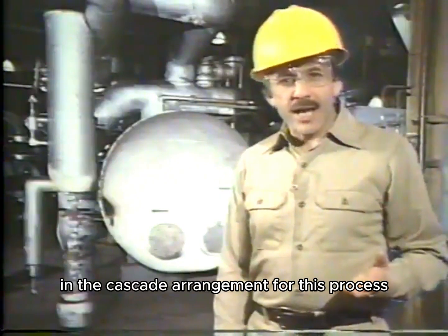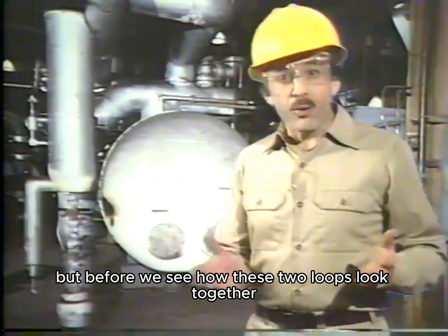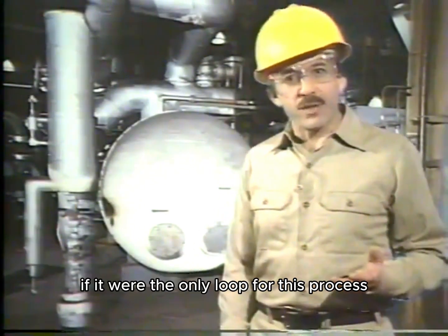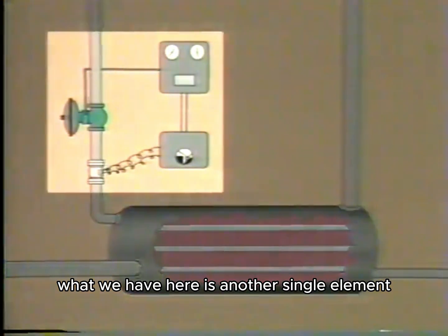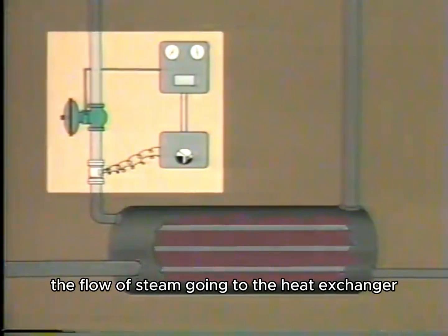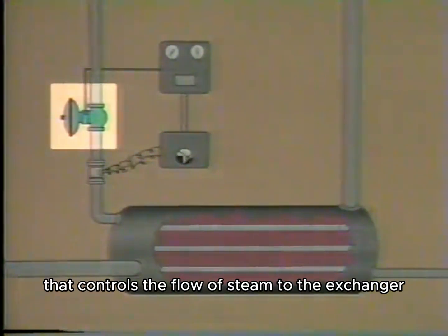Now, we said that in the cascade arrangement for this process, the secondary control loop is combined with the primary control loop. But before we see how these two loops look together, let's see how the secondary control loop might look if it were the only loop for this process. What we have here is another single-element control loop. We're monitoring one variable, the flow of steam going to the heat exchanger. This information is used to adjust the steam flow control valve that controls the flow of steam to the exchanger.